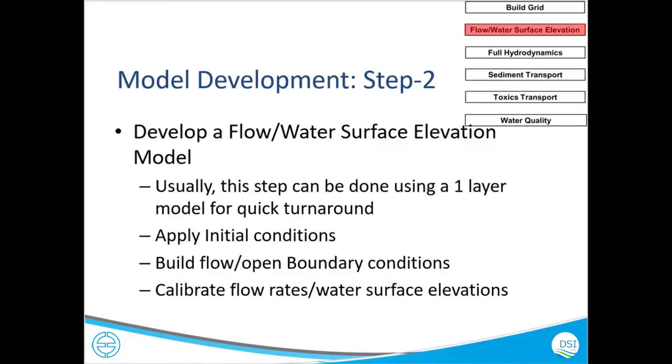So I mean, this thing I didn't do it very well while I was starting. I just created 10 layers and let the model run. It would take 20 hours to run, and then after 20 hours I realized, oh, I screwed up. If it's one layer, it will take two hours to run your whole simulation. So just run with one layer, be sure, compare your water surface elevation at different regions, and when you think your water surface elevations are good, then just introduce the number of layers you want to do.